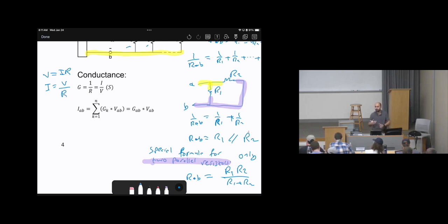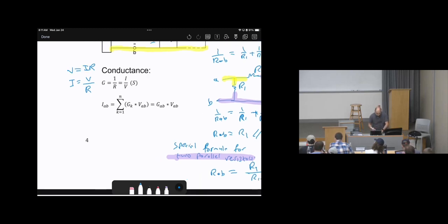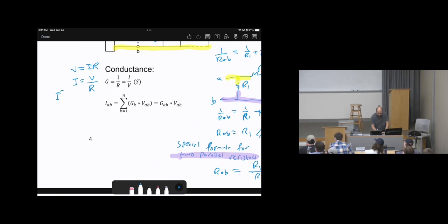Sometimes, most likely when we build software, especially on large networks, we will write it as a matrix. So I as a vector, the resistance as a matrix, so it will be R inverse times V. That's how we do the calculation when we deal with very large systems, to make some analysis in current calculation. For example, for university electrical connection systems, we need to do some studies.